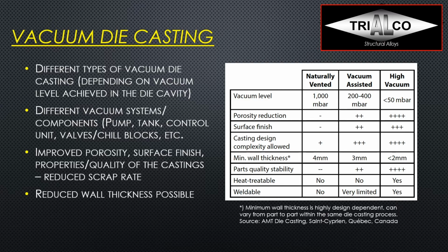In general, you get better mechanical properties and a better quality of the castings. So if someone tells you that vacuum just costs you more money, well then you are probably doing something wrong. Because if you apply vacuum where it makes sense and in the right way, it should actually help you a lot and should really reduce your scrap rate and make better castings. So in the end, it should actually save you money.